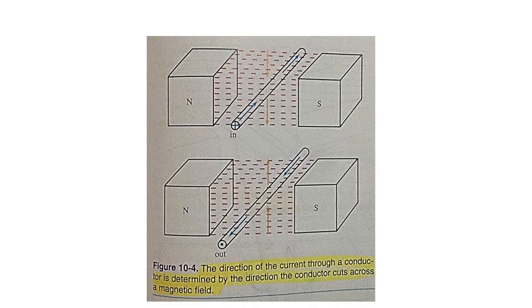This voltage can be increased by winding the armature with many turns of wire, by increasing its speed of rotation, or both. Reviewing what was learned in Chapter 6, this link can be expressed by the mathematical equation shown,